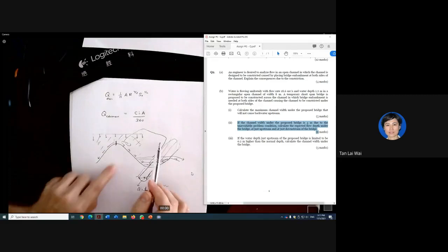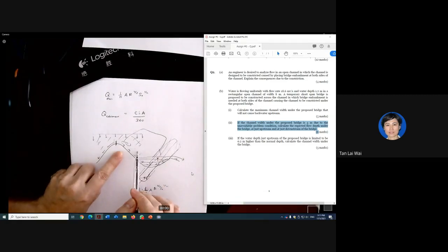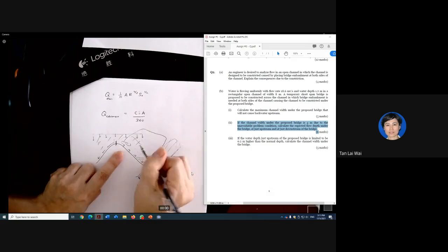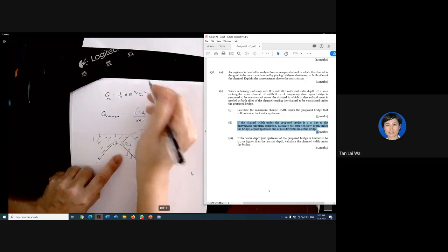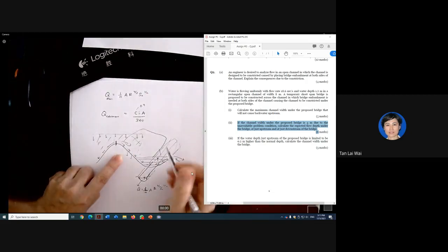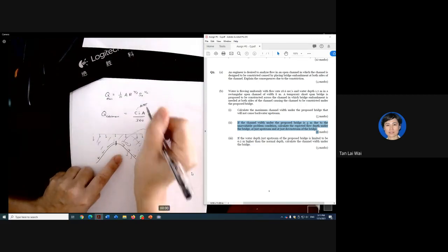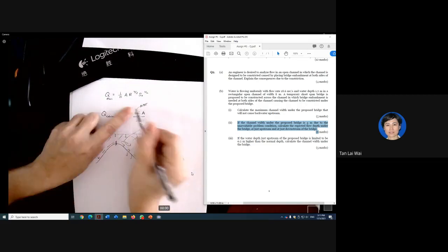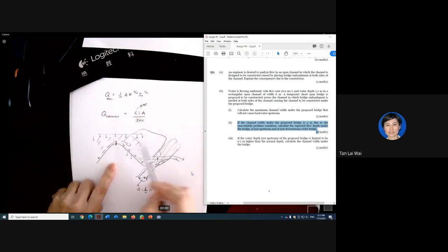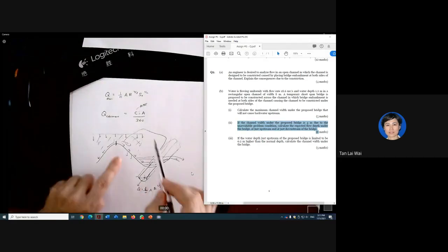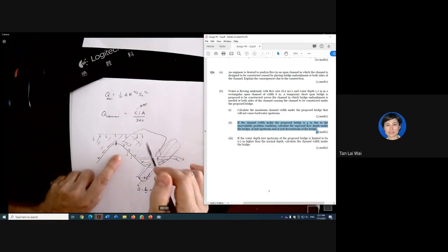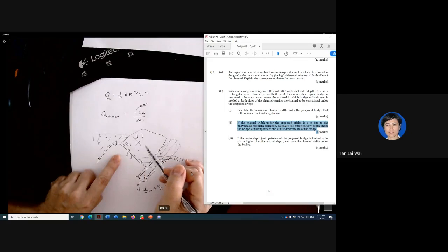Imagine the whole area, you have paved it. That means you put concrete on it. That means no water is going to seep into the ground. That means this is almost 0.9 or higher, 0.95. Let's imagine if C is equal to 1. That means you only have I times A. How much rainfall falls will go into this drain. But normally, it will get slowed down.